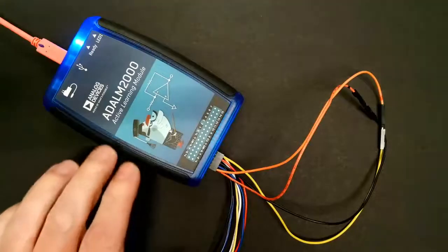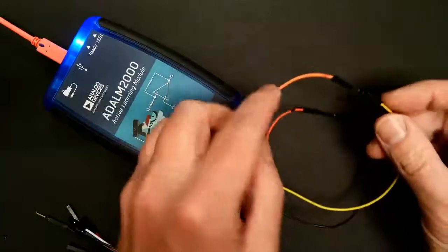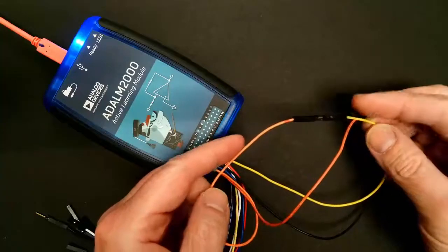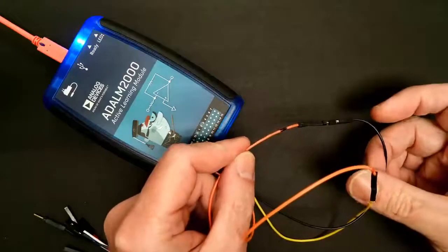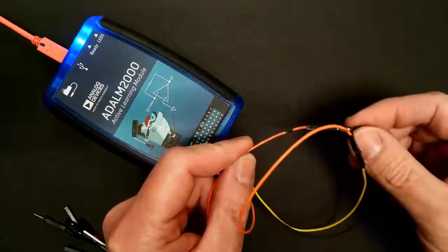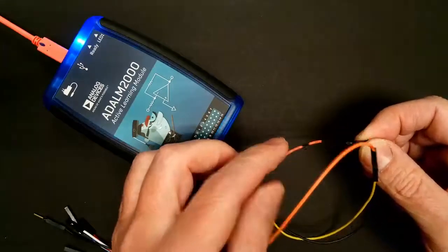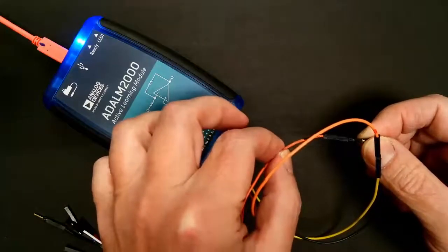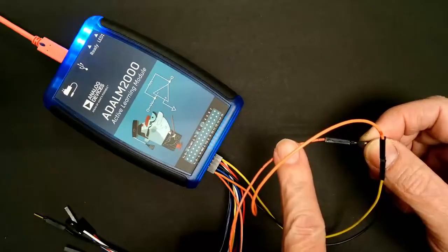For using the oscilloscope in our situation here, I've taken the waveform generator channel, which is the yellow wire, and I've hooked it up to the channel 1 input for the oscilloscope. Also, I've taken the ground pin. Remember, the waveform generator is single ended, so it has to have a ground connection. And I've wired that into the negative terminal of the channel 1 oscilloscope. Again, the oscilloscope is a differential measurement.